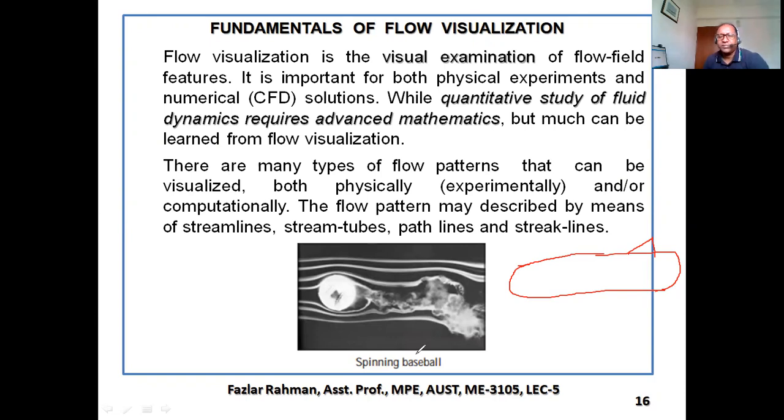But there is an opportunity: you make the submarine at a smaller size, 1,000 times less or 100 times less, but the shape remains the same. It's called a model. Make it from ship material, wood, or foam. Then you put that in the wind tunnel, and air will flow. If you generate some smoke, you can see how fluid flows around the fin or around the body of the submarine. This is called flow visualization.